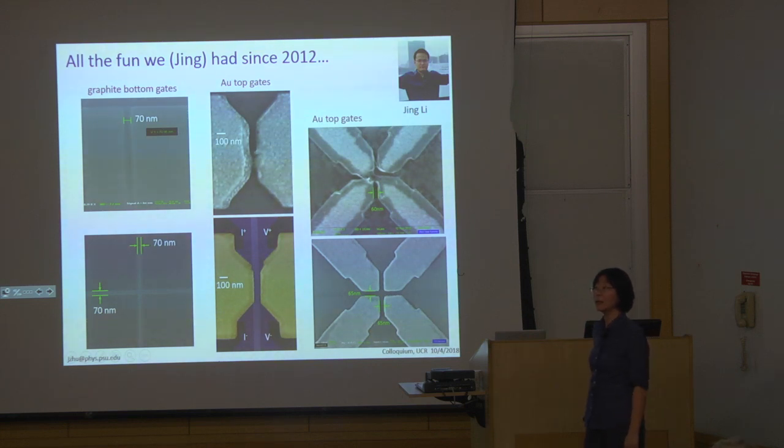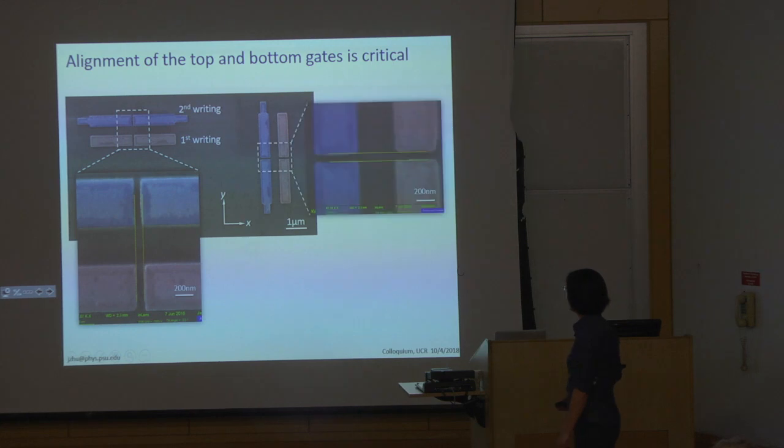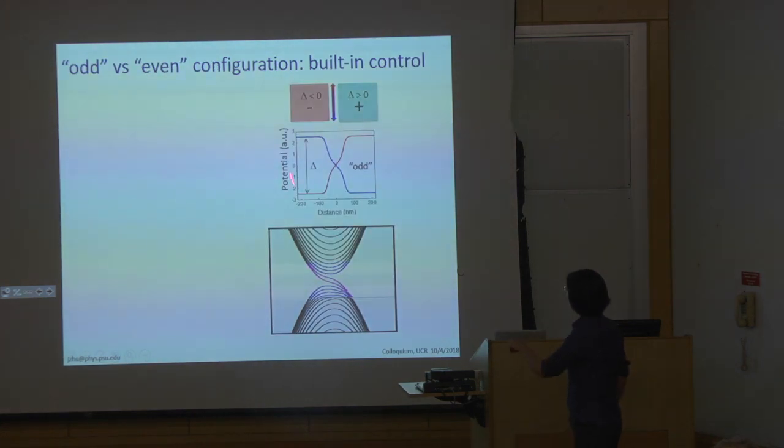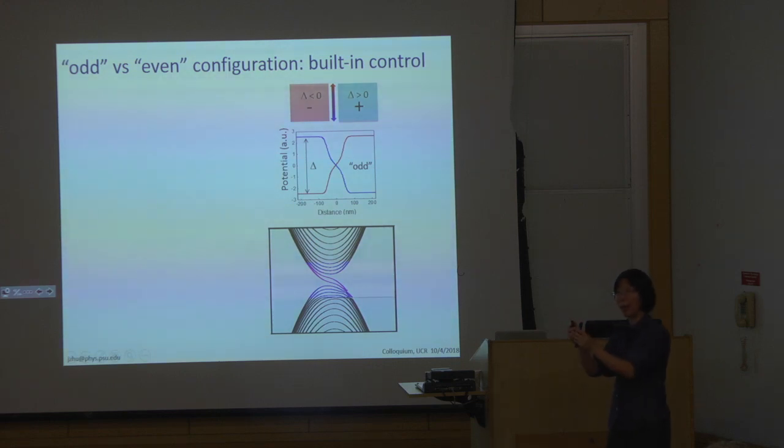So we're moving into what happens when you open it up. Oh, okay, good. So I'm going there. Remember this band structure that I showed you? If you make this real wide, now you have a wide nanoribbon, and states living inside that wide ribbon now drop lower in energy. So effectively, now your quantum wires are living inside a smaller gap. And I want to make that gap as large as possible, so that's why you want to go narrow as far as lithography allows.